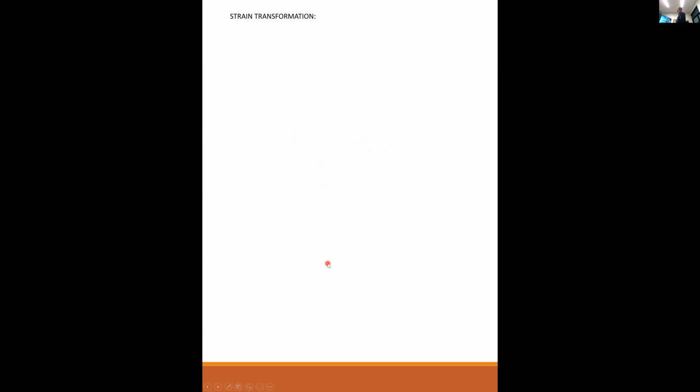Small angle theory. And so there's a component of this little guy right along there that is oriented in the x prime direction. And that little piece right there is gamma xy dy cosine theta. And I transpose that to over here, and those are your 3 components.